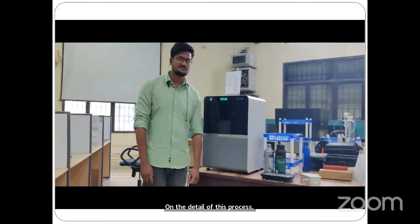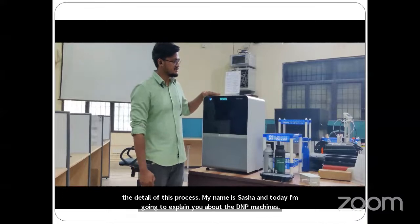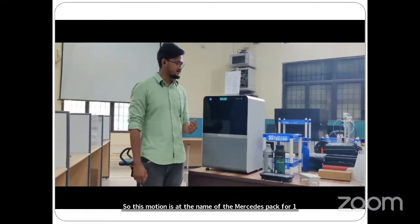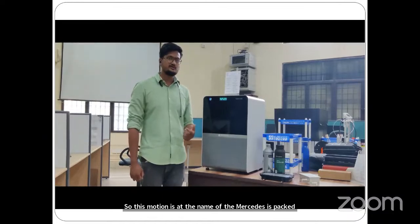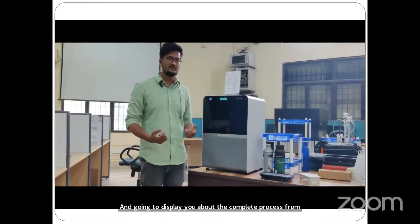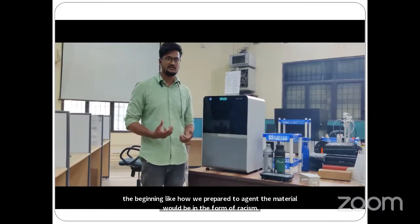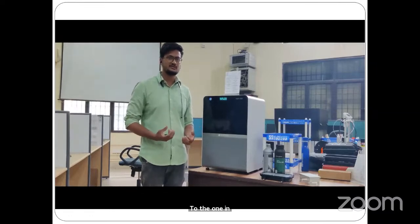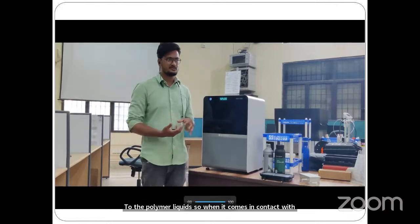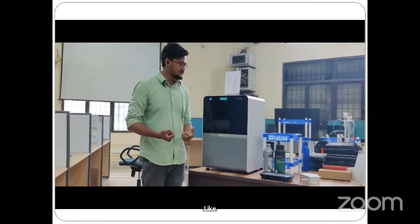Hello everyone, my name is Suranjan, and today I am going to explain the DLP machine. The name of the machine is FAPRO 1000, and the manufacturer is 3D Systems. I am going to explain the complete process from the beginning, like how we prepare the resin. The material will be in the form of resin, which is a photoreactive polymer liquid. So when it comes in contact with light, UV light or some kind of projector, it gets cured. Like that, the build happens. We will discuss that later on.